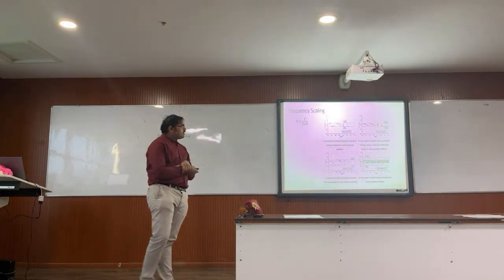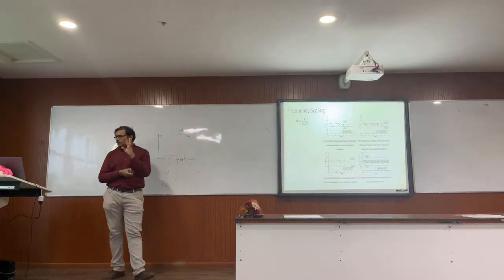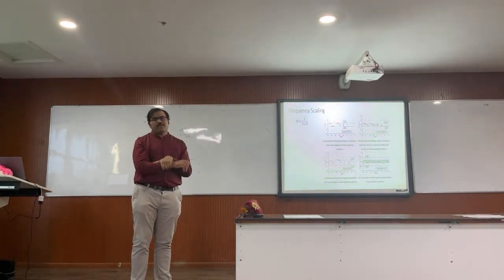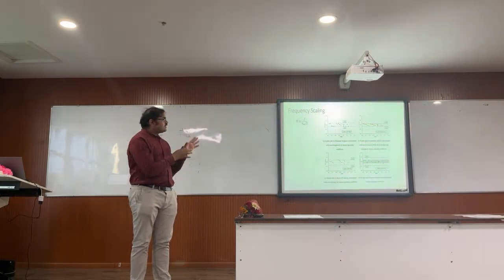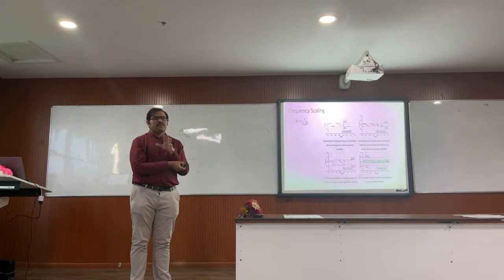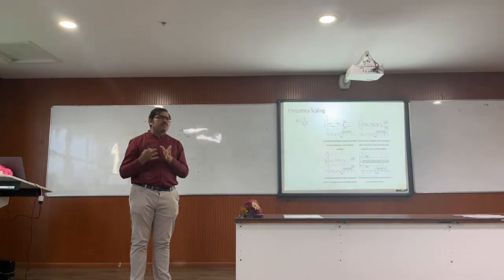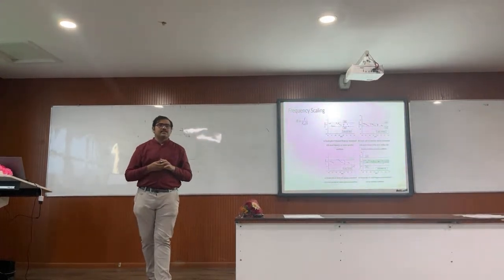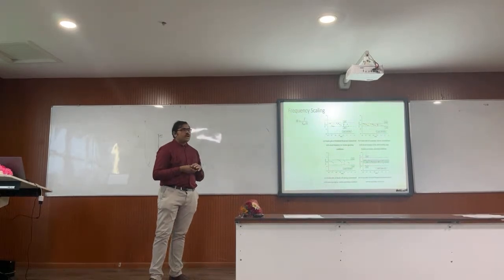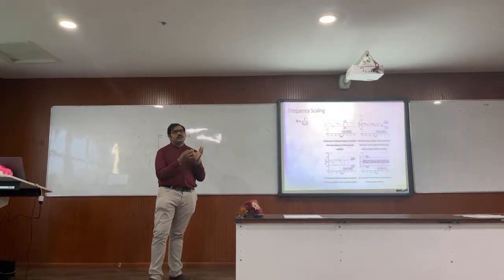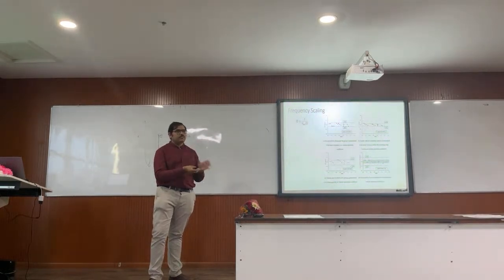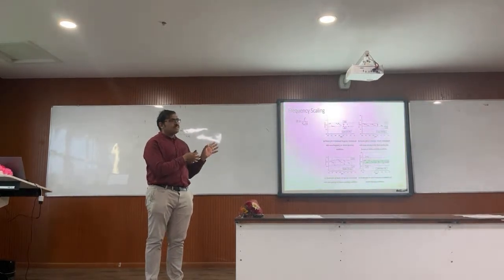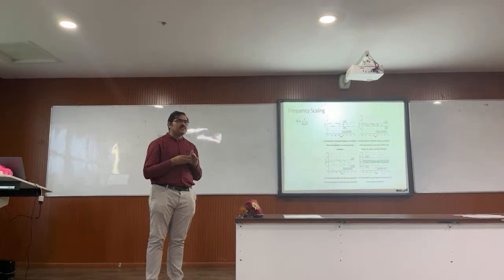In today's talk I have discussed two kinds of unsteadiness of the shock. One is in intakes, in the hypersonic domain, where the Mach number is 6, while the other is in the supersonic domain, where the Mach numbers are more in the range of 1.5, 2, and so on. In supersonic flow, this is completely an internal duct problem. The hypersonic intake start is a different kind of problem, where there is some duct and something happening external to the duct.